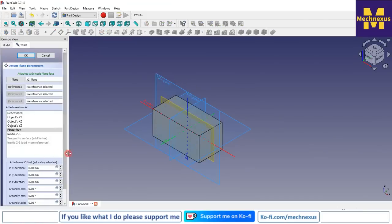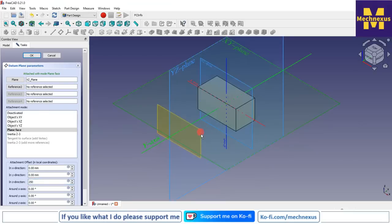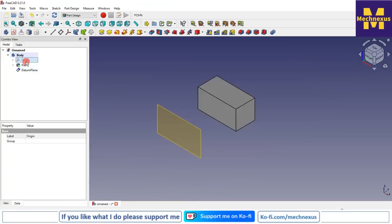So here in the Z direction I will give a 250 distance. So you can see that a datum plane is created and I will say OK. Hide my origin plane by pressing the space bar. Now you can see here a blue tick symbol, it is for the rebuild. So click on the refresh icon or press F5 on your keyboard.